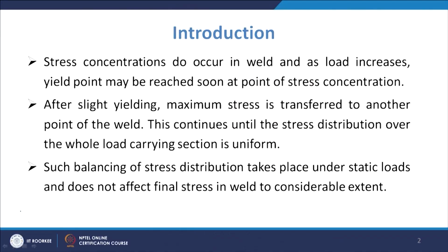It is taken into consideration how long the material can sustain load. In most cases you will have the presence of stress concentration in the weld, and as the load increases, the yield point may be reached soon at the point of stress concentration.